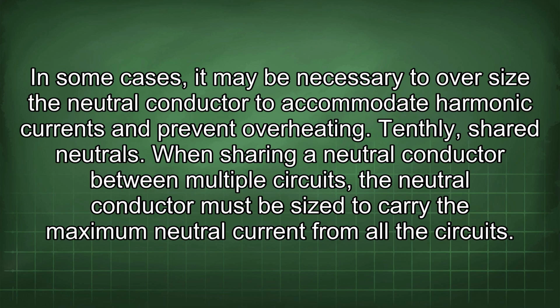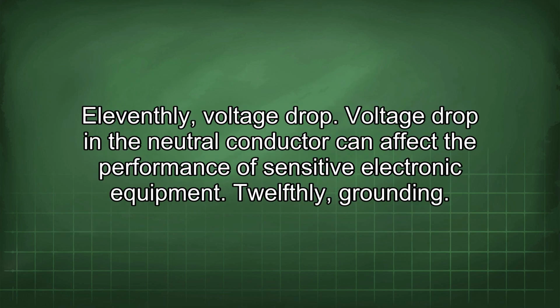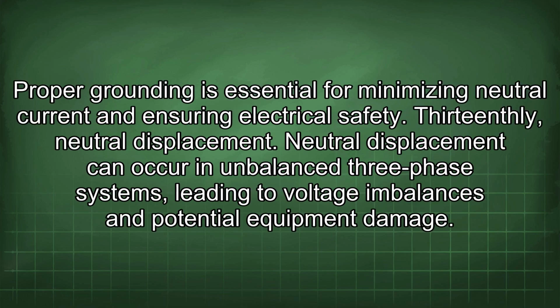When sharing a neutral conductor between multiple circuits, the neutral conductor must be sized to carry the maximum neutral current from all the circuits. 11thly, voltage drop. Voltage drop in the neutral conductor can affect the performance of sensitive electronic equipment. 12thly, grounding. Proper grounding is essential for minimizing neutral current and ensuring electrical safety.